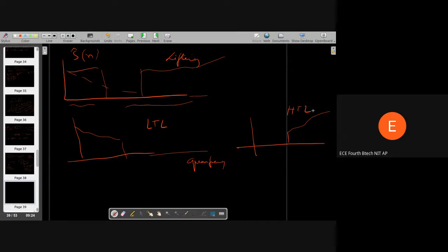So now from this, what we have found is that these first few components of this Cepstrum represent your slowly varying system, because the system is slowly varying compared to the excitation, as we have seen if you take the Fourier magnitude spectrum.